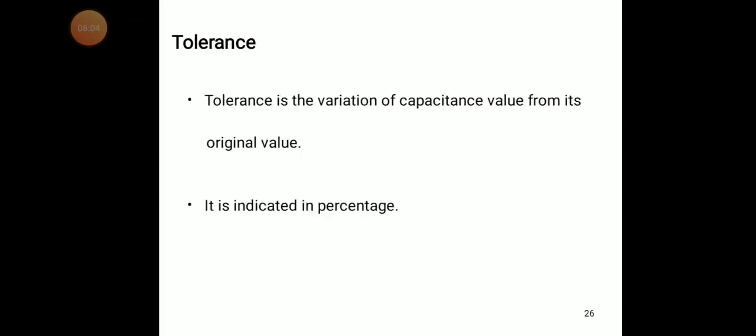Already you know the tolerance. Tolerance is the variation of capacitance value from its original value. Each component has a particular specified value, but whenever we use that component practically, it may have some deviation, either positive or negative, a tolerance band.